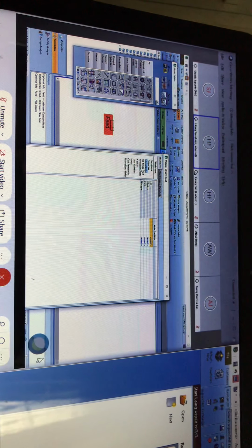Click on compositions there, then check the PFD given at the beginning of the questions. They already state the compositions of your feed. For HCl, about 50%, so it's 0.5. Ethylene is 48%, so that's why it's 0.48.